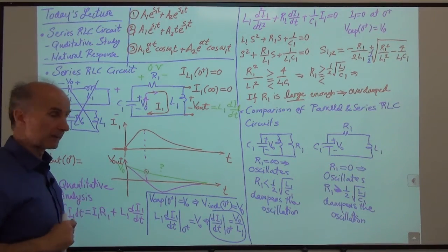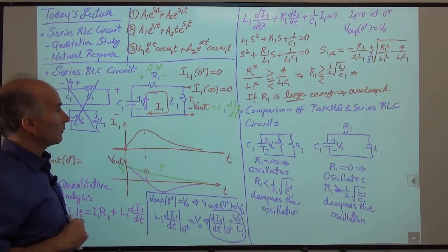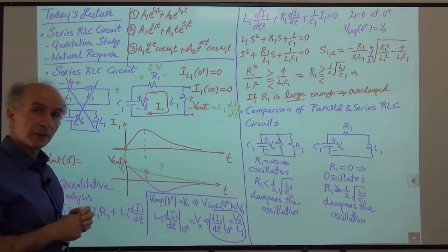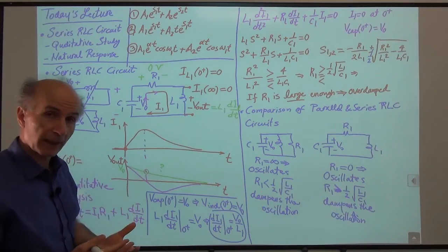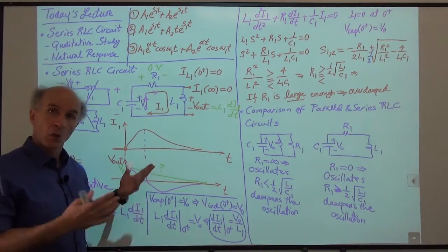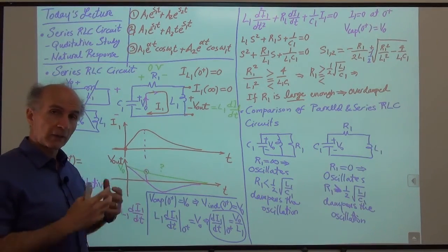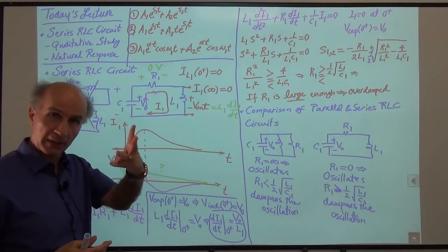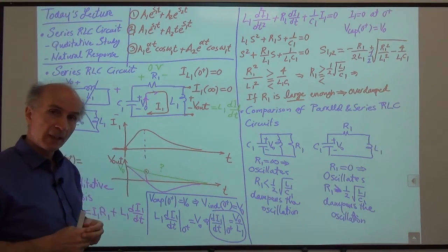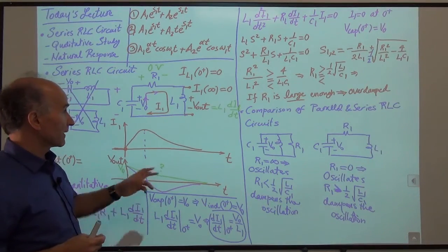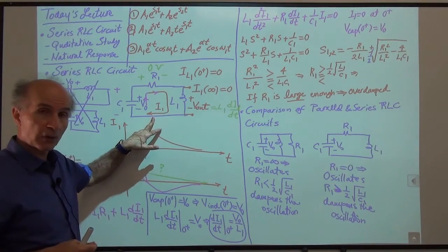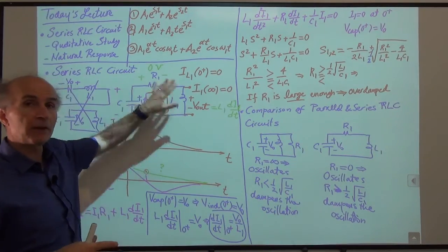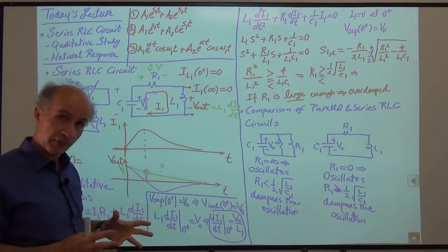All right, so that's easy. But one more parameter of interest to us is the voltage across this capacitor. And we'd like to calculate that based on what we've done here, or independently, right, as a function of time. So again, that voltage should satisfy one of these three cases, three responses. Of course, if, for example, the current through the network has an overdamped response, then everything in the network has an overdamped response, right?